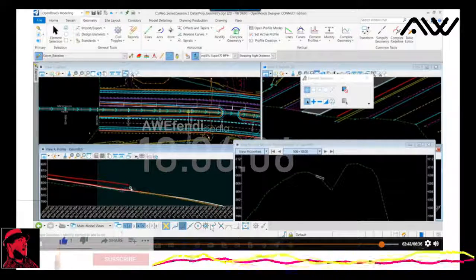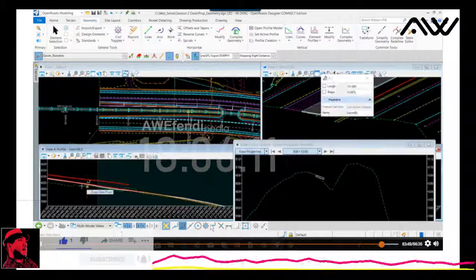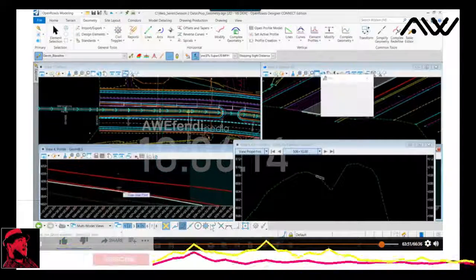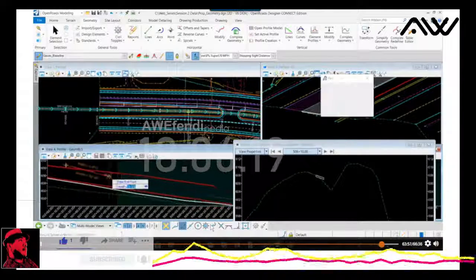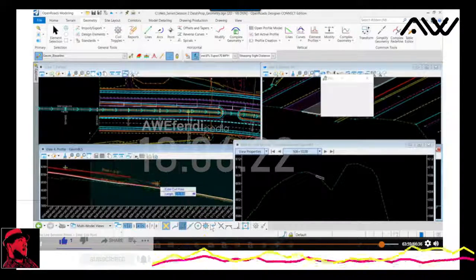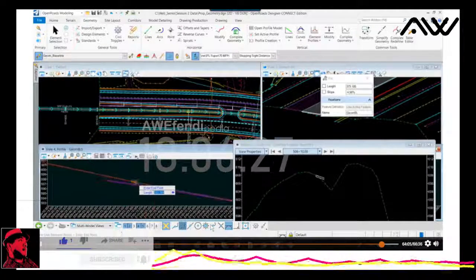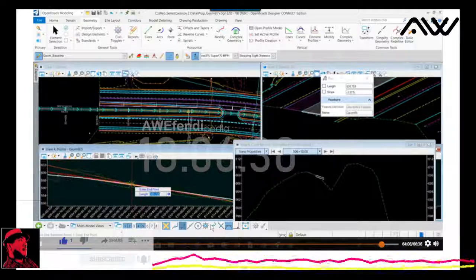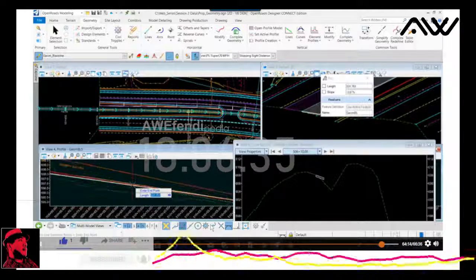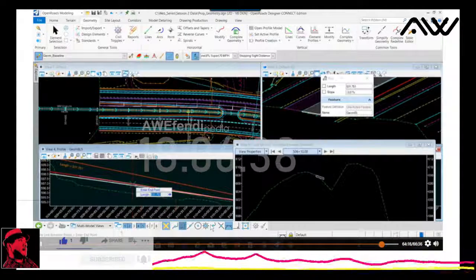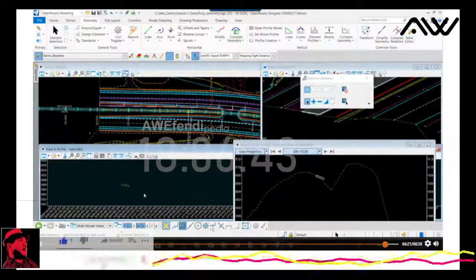To do that, I'm going to go back. I'm going to use profile line again. I'm going to just draw a tangent area, again, a straight vertical line. Now I'm going to use the MicroStation tangent snap. Let me get this view proper. And I'm going to be sure and select a tangent location to my PGL, okay? And data point. And so now I have a taper that's tangent again to that vertical curve.